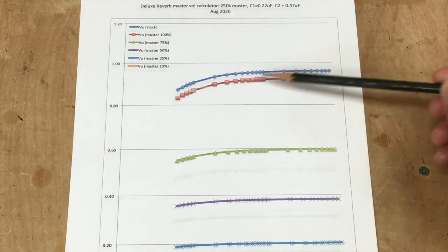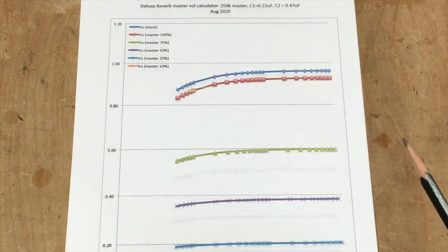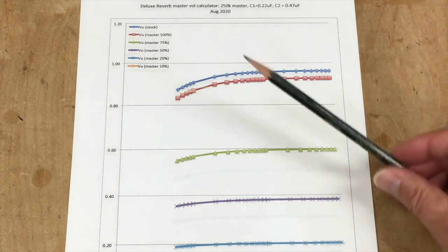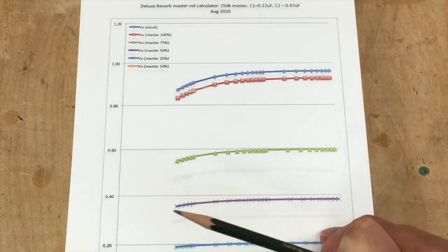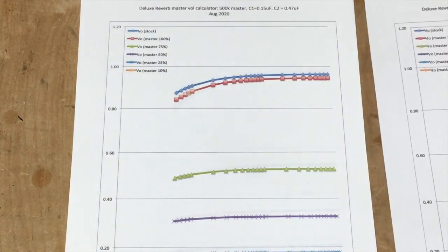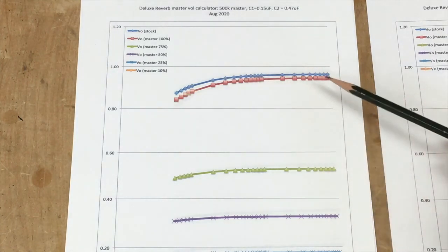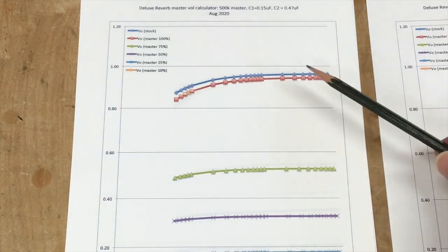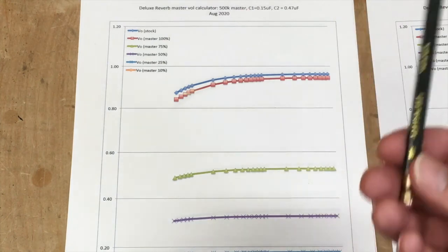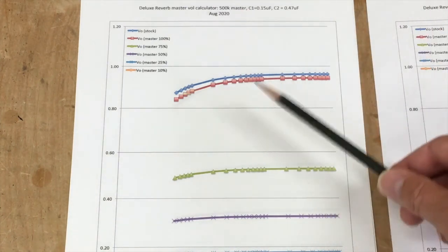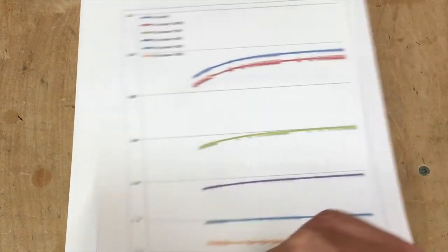We've lost a little bit of voltage, but that may be immaterial. So the plan is that I'm going to start with the 500K master volume, that is this one. And if you run into problems with noise and stability that we can't eradicate with shielded cable or wire dressing, etc., then this is our backup plan right here.